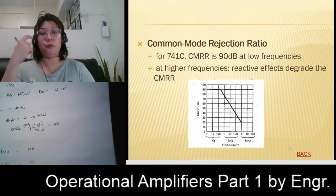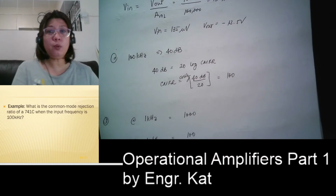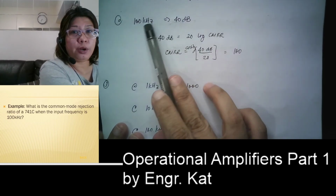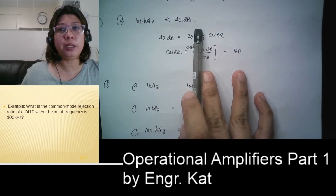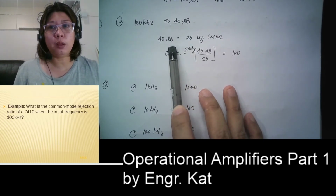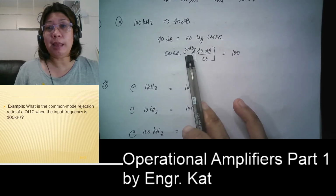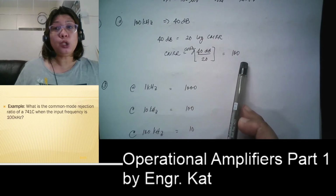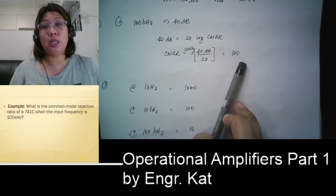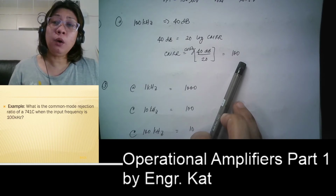So what do we mean by 40 dB? In the figure earlier, at 100 kilohertz, your CMRR is equivalent to 40 dB. If we are going to get the CMRR out of 40 dB, 40 dB is equivalent to 20 log of your CMRR. So CMRR is 40 divided by 20 and then the anti-logarithm. That means 100. Earlier, if it is 90 dB, it is around 31,000 times, so the differential input is amplified 31,000 times better compared with your common mode input.